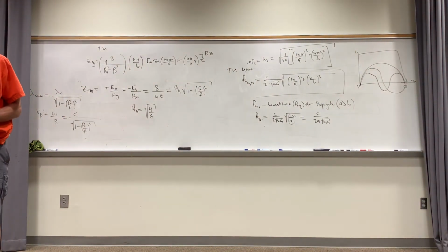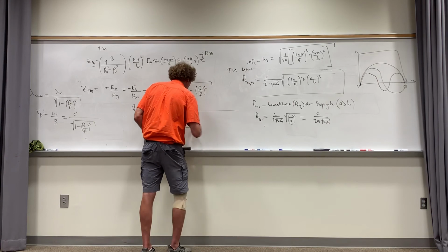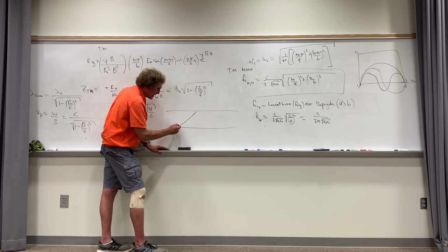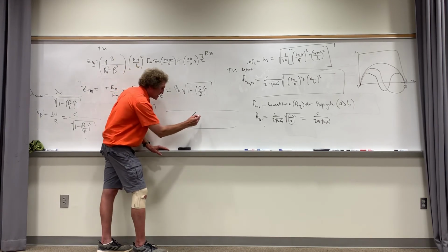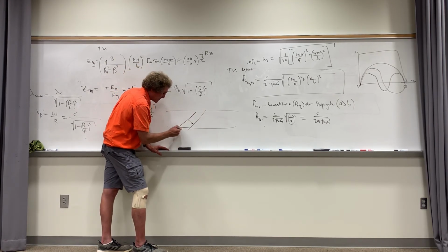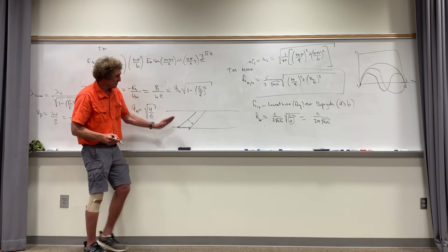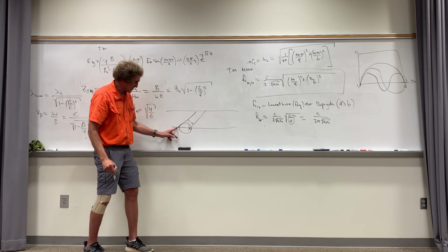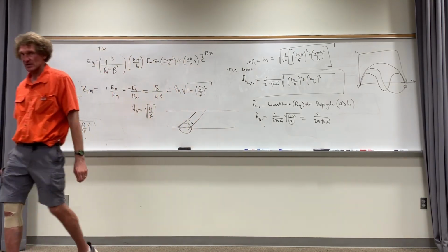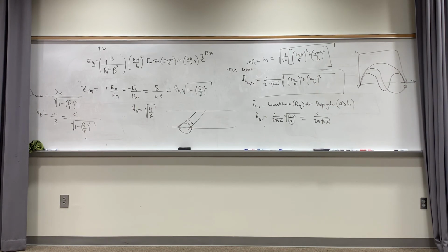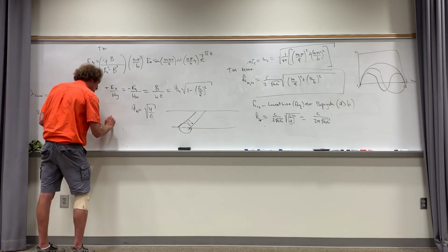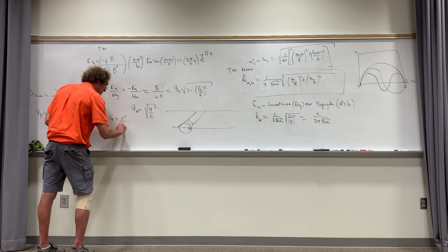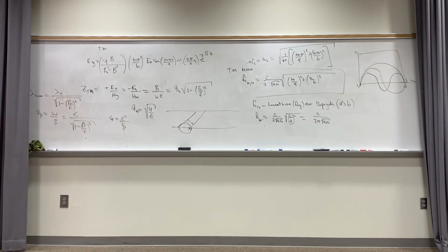Well, phase velocity in a guide has to do with this. When you think about a guide and its cross sections, suppose we have a constant phase surface here moving this way, and a little bit later it's here. This moved a small amount, but here it moved a large amount. Y'all see that? The phase velocity has to do with the rate that this crest intersects this bottom surface and how fast that point is moving. That's all the phase velocity is in a waveguide. The group velocity is going to be much less than the speed of light. If you want the actual velocity of energy, you take c squared and divide it by the phase velocity, and you get the actual group velocity. I'll get into that next time, okay?